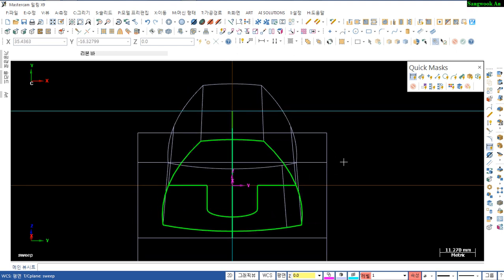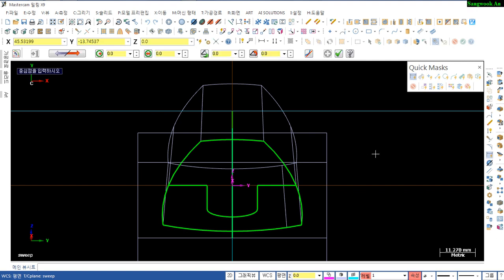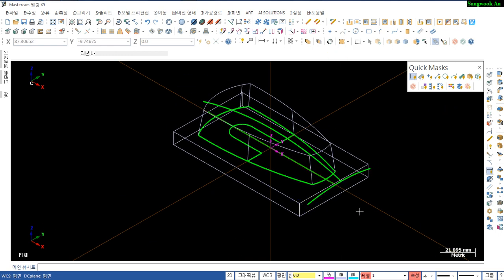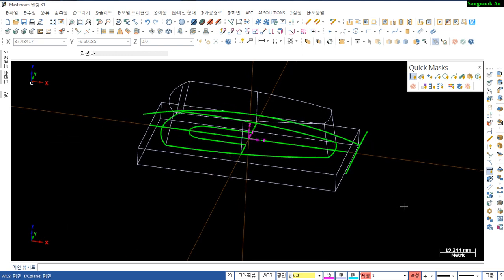So hold the arc and press the Shift key and select this position, and write down the position, 0, minus 80. Radius 80. So at this point, yes, OK, and plane top view, and master view.